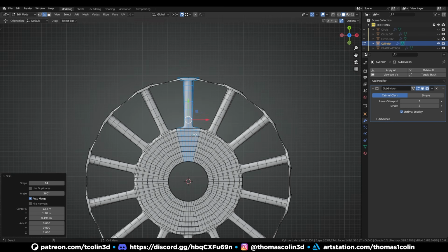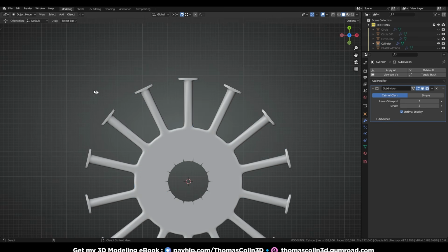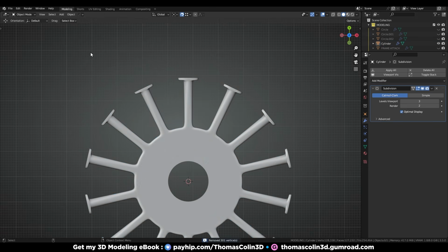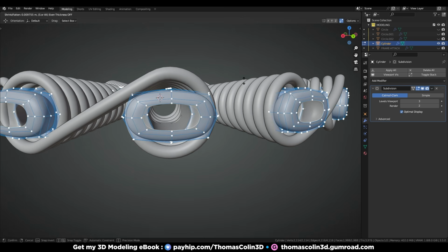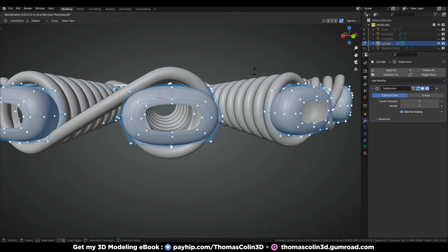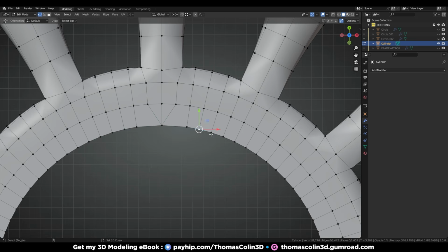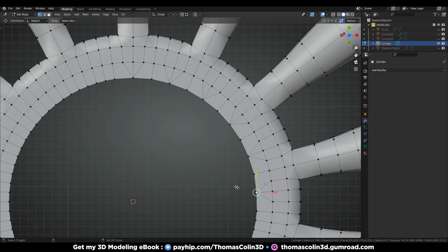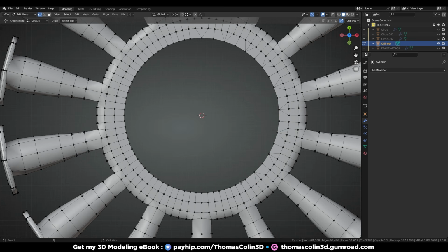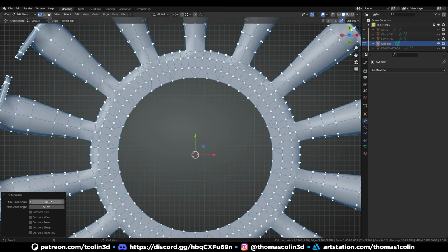Use the spin tool again to create a radial array. Merge the vertices by distance. You can press Alt-S to slightly inflate the model to make it bigger. Here, collapse and merge the vertices to reduce the poly count until the model matches the desired shape. Press Alt-J and increase the max shape angle to convert triangles into quads.